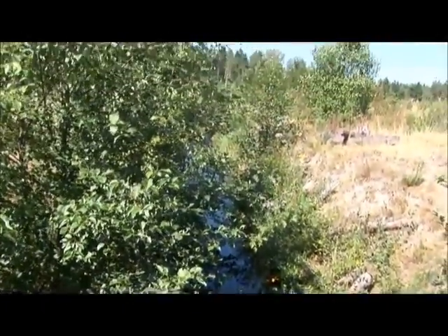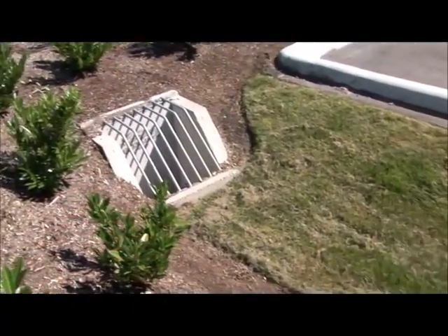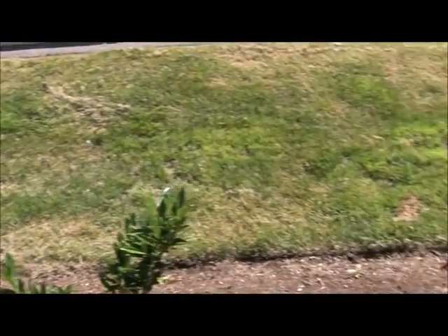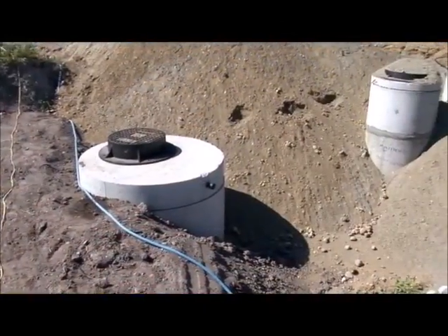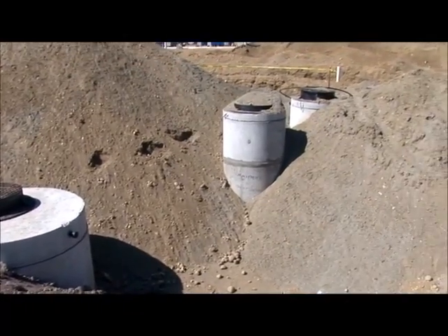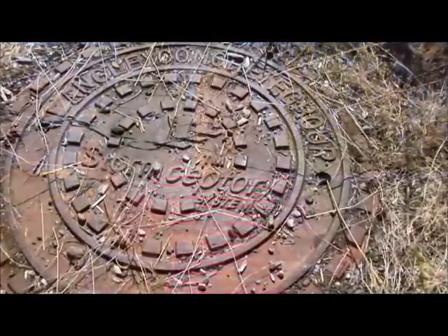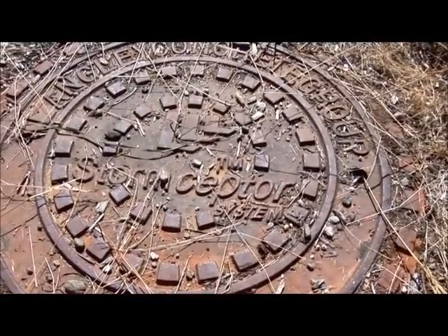This has worked in the city of Surrey. In the Campbell Heights area, we have a treatment train for water quality. The industrial land has to have 50% of its frontage drain to bioswales of some sort. Their parking areas have to all go to oil grease interceptors at the property line. The city pipe system is actually a perforated pipe to try to get infiltration as much as we can. Before it enters the creek, it goes into a mechanical device, which is a storm scepter, to clean any sediments